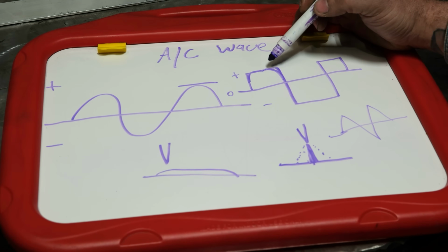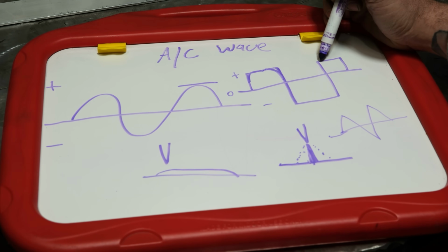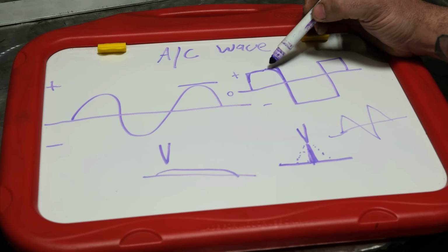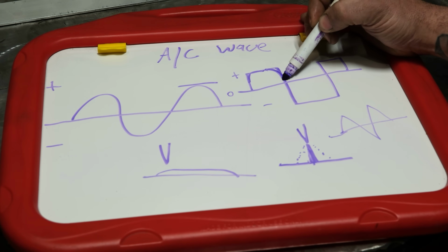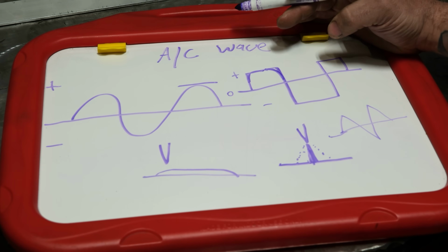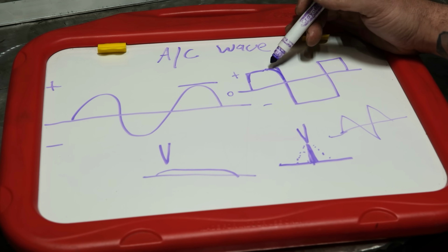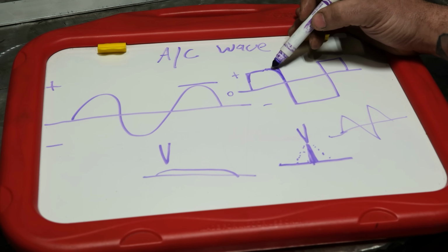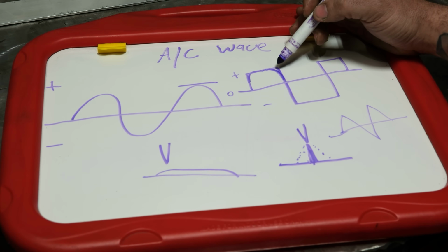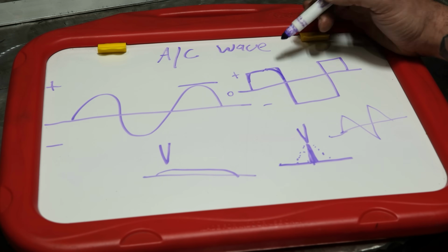Well, a lot of that comes from this: with that square wave, that abrupt voltage change produces that pitch. By changing it and doing a soft square wave, it can quiet the noise down significantly. Now, not all machines can do that, and it's mostly done just for noise reduction. It doesn't really offer any performance increase other than noise reduction.